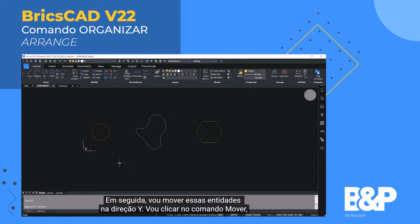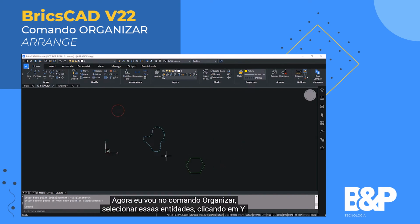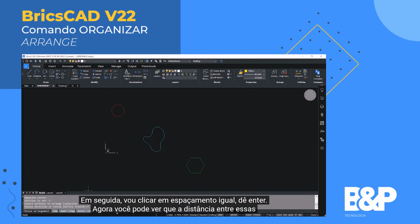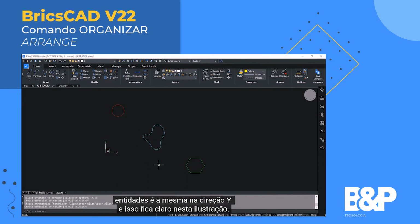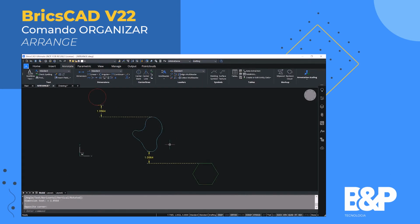Next, I'll move these entities in the y direction. I'll click on move command. Now I'll give arrange command. Select these entities, click on Y, then I'll click on equally spaced. Give enter. Now you can see that the distance between these entities is the same in the y direction. And that is clear from this illustration.